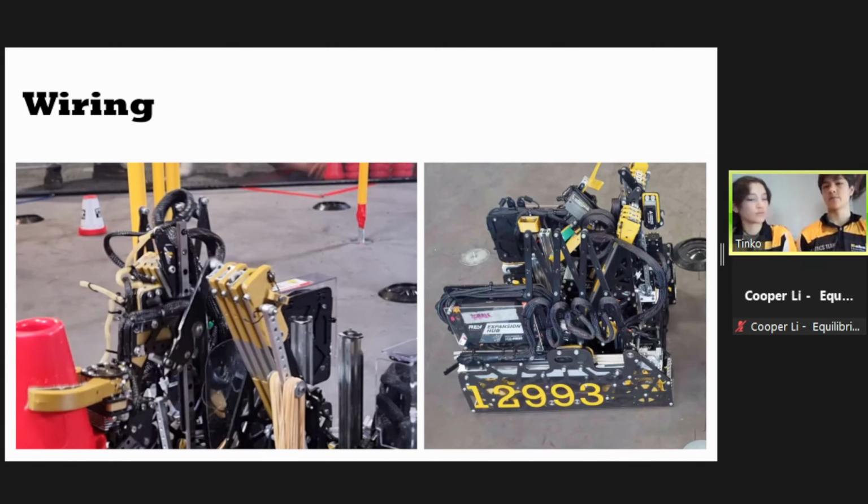We like to have, obviously in our last year's design we didn't do this quite well, but if you can have the REV hubs closer together, that means that the connecting cables, for example, the RS485 and also the power cables, can be shorter. And it means that if you need to replace one of them, it's less of a task.